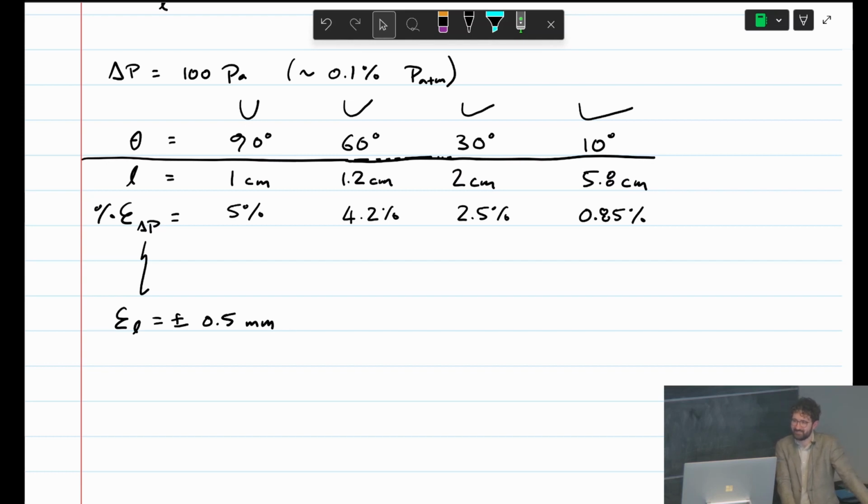Okay, maybe Ian? One downside of a manometer is it could be very large if you're trying to deal with larger pressures. Yeah. Especially if you're inclining it, you can start going a long way out. Yeah, they can get pretty big. So that's why mercury is often used in barometers, because it has such a high density. So if you have to measure a high pressure change, you want something with a really high density, so that the height is less for the same pressure change.